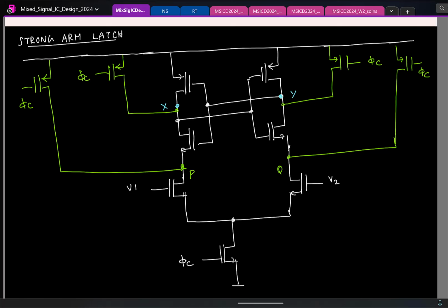Great. So by the way, this is called latch because if you see what I have is a CMOS inverter. The output of the first CMOS inverter goes as the input of the next CMOS inverter, and the output of the second CMOS inverter goes back to the first one. It's like two snakes biting their heads and tails. So people who have taken any digital course should be able to recognize this. What is this? What is it called? I mean, this is called the latch, right?